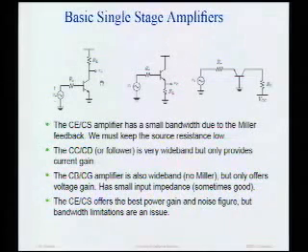So even if we don't have a limitation coming from the source, from the load we have output capacitance, and that produces a pole with that load resistance. So that's bandwidth reduction. And you're precisely right. If I want to get high gain, I need to use either a lot of current to get lots of transconductance, or I need to use a large resistor. And if I use a large resistor, that's going to reduce the amount of swing I have at the output, and it's also going to have a lot of capacitance and a high RC time constant. But I'm actually looking for something else.